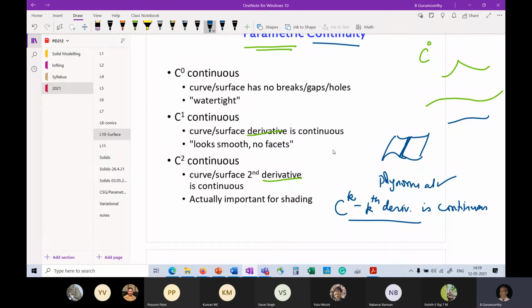So it is purely a property of the representation that you have of the curve. I compute the derivative, see if it is continuous at the junction, and you are set. You may recall that we did this for the spline curve, because it is defined piecewise. It is defined one way in one segment and another way in another segment. But we showed that at the junction, it is always Ck minus 2 continuous, which means that if K is the order of the curve, then it's continuous up to two orders less derivatives than that. So if I have a cubic, K is 4, I have C2 continuity, meaning curvature continuity is guaranteed. Again, continuity you talk of at the junction.